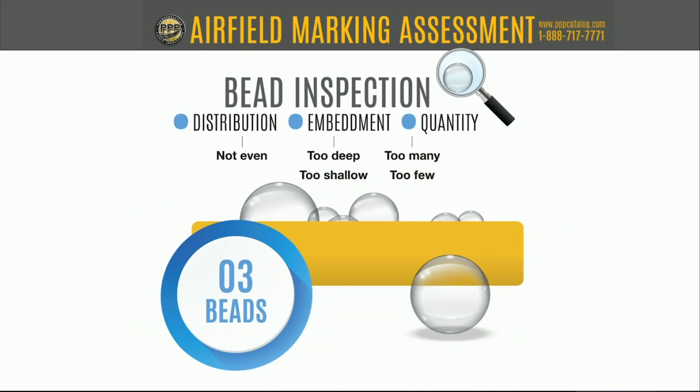That's probably, again, the biggest issue I see a lot of times. We were out looking at some marking materials recently, and he was going way too fast. He had a line driver, and he was moving along pretty quick. I said, well, you need to slow down because you need to get more paint on the ground, or you're going to have to go with a bigger tip, and so on and so forth. And so when he slowed down, but he didn't change the bead drop.